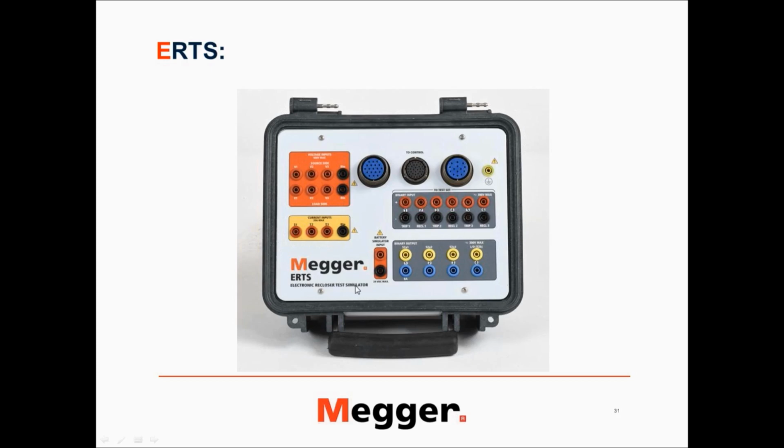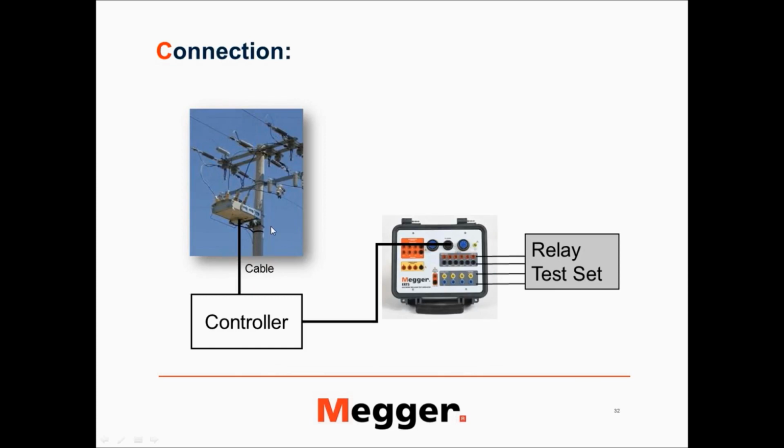So it has the 14-pin, 19-pin, and the 32-pin plugs available. What you're going to do in this case is take the same cable. You can have a spare cable of the same type that you're trying to test on the controller. Connect it between here and here, whichever it is: if it is a 14-pin, insert it in the 14-pin cable insert. If it is a 19-pin, insert it here. If it is a 32-pin, insert it here.